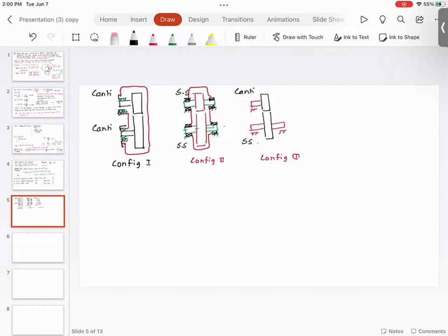In this case, since the shaft is supported on both sides, the amount of loading that is going to come on the shaft will be less. So it basically will reduce the size of the bearing. But clearly, you need the shaft to be extended on either side. And because of the simply supported configuration, the shaft size would be less. But again, the housing size is going to be big. Then you can have this cantilevered.